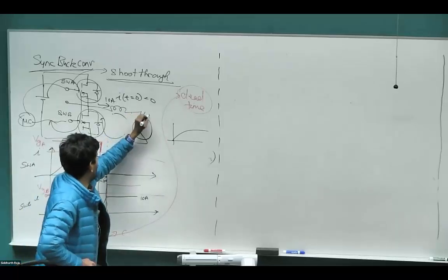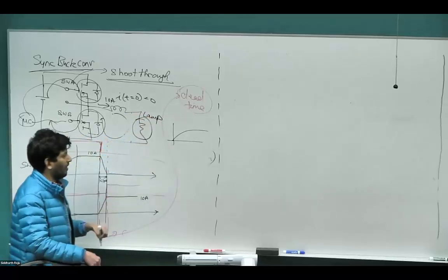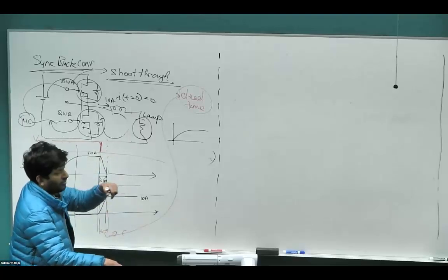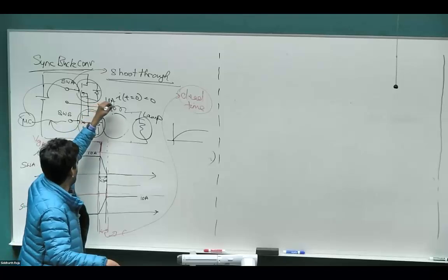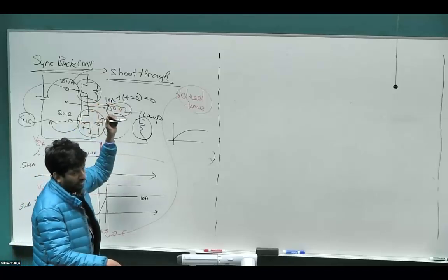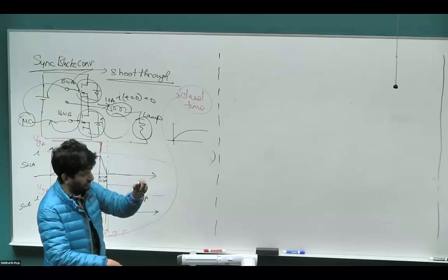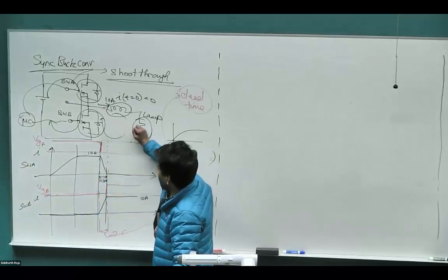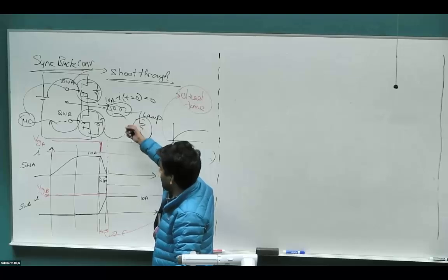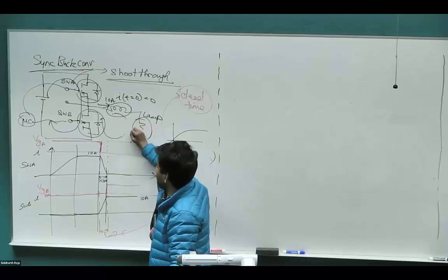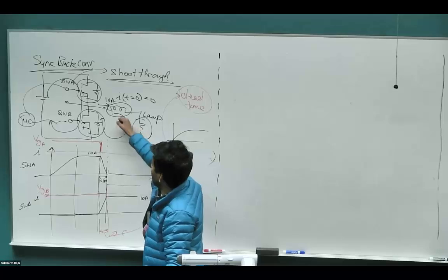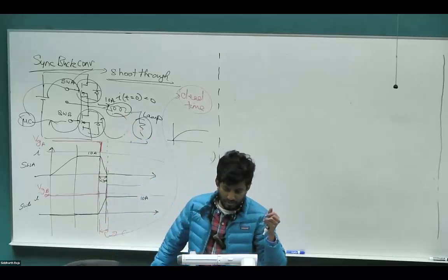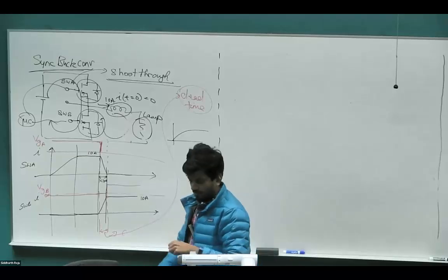But the tungsten filament and the whole bunch of wiring and the cable, all of those going from the inverter and so on, have an inductive effect. So we are basically modeling the same thing that's there on the table. And we're only looking at RL loads because when the motor typically operates in and around the desired fundamental frequency, it does behave like an inductive resistive network. When you go to very high frequencies, everything becomes capacitance, but that's not something we're going to be worried about.